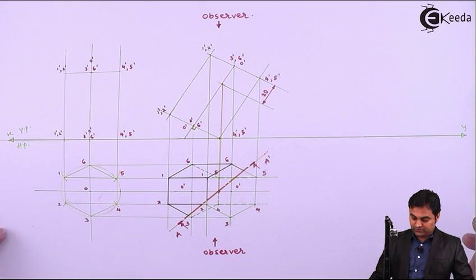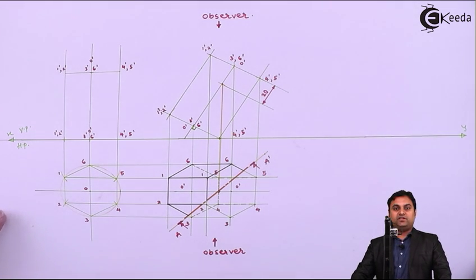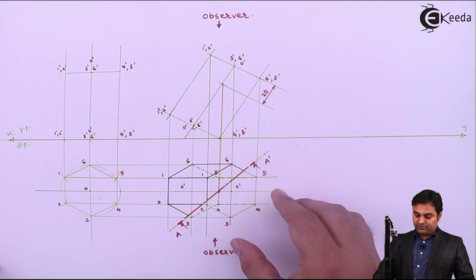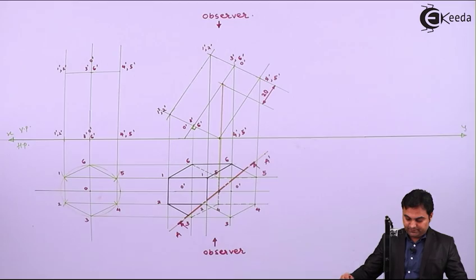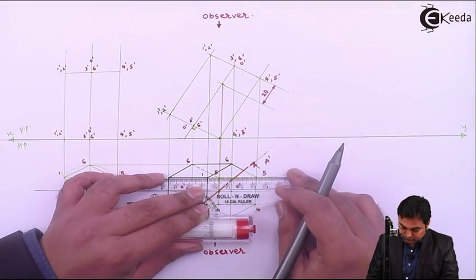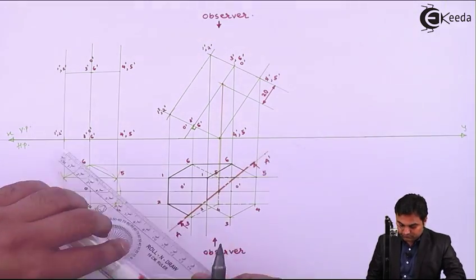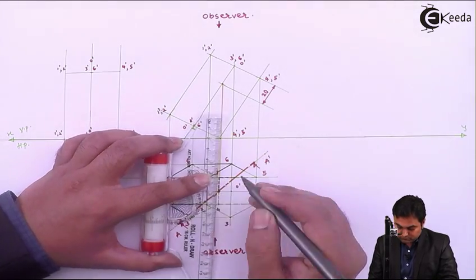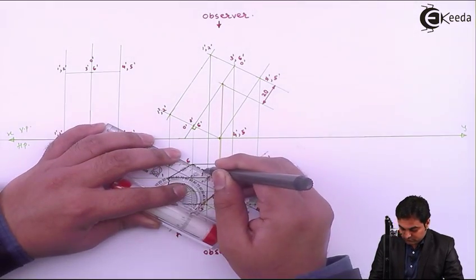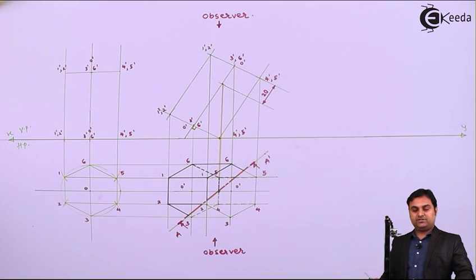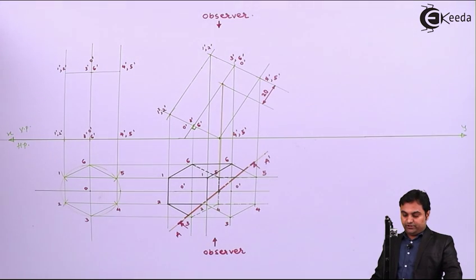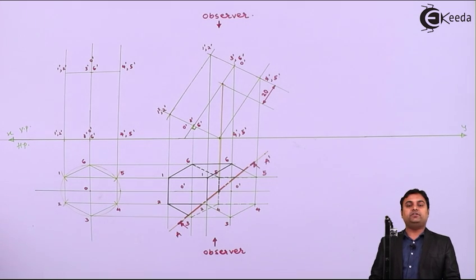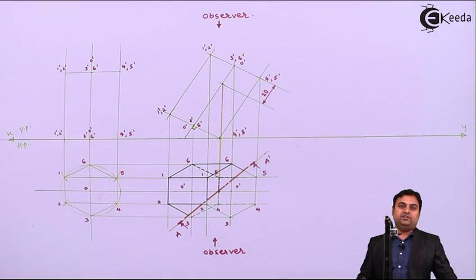Cutting plane AA dash. Now as we see here, the portion which is in front of the observer, that is removed, and whatever is behind, that is retained. Next, I need to project these points up so that we get the sectional front view, and before doing that, now when we have located the cutting plane, I can make this initial condition dark.